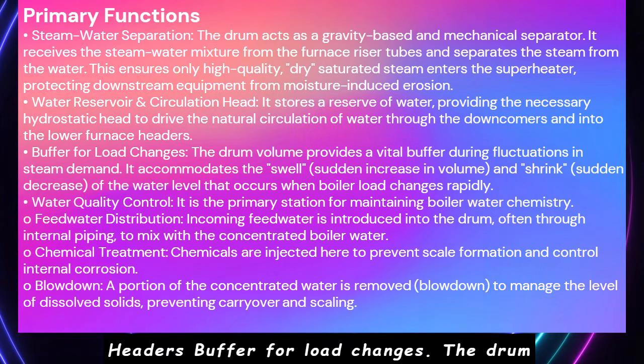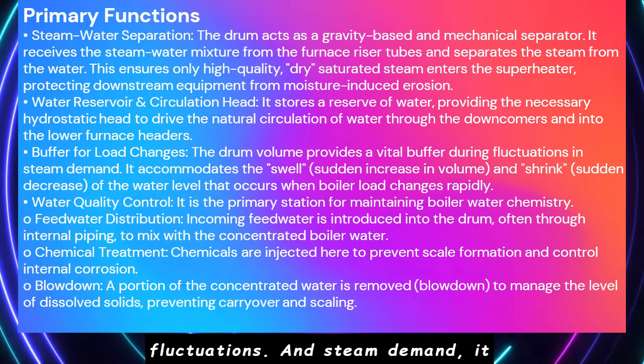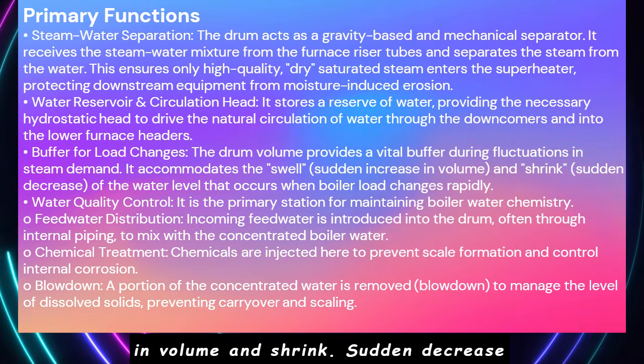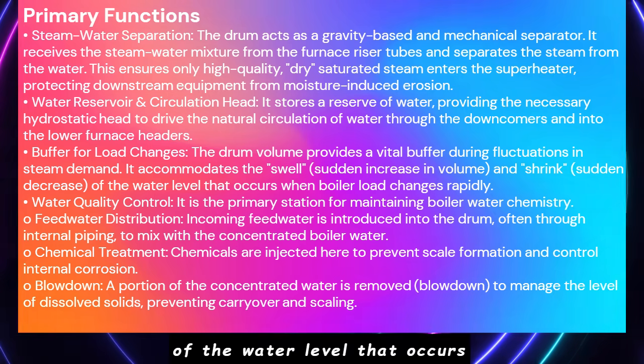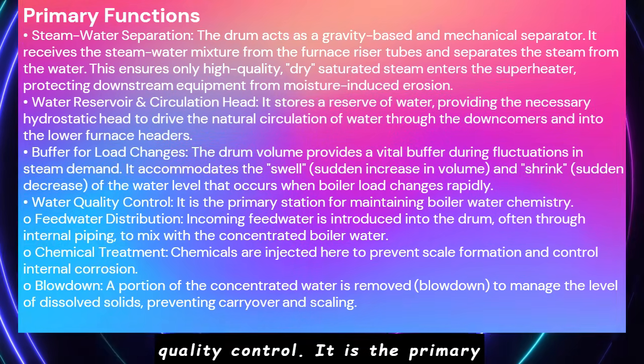Buffer for load changes. The drum volume provides a vital buffer during fluctuations in steam demand. It accommodates the swell, sudden increase in volume, and shrink, sudden decrease, of the water level that occurs when boiler load changes rapidly. Water quality control.